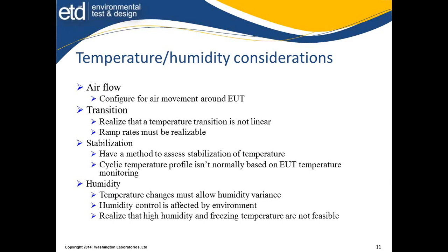Realize that with humidity, temperature changes must allow for a humidity variance, especially if these temperature changes are somewhat rapid. You've got to change, the humidity will vary, and then you can recover it maybe, but it's going to change at some function. So realize holding a solid humidity while we change temperature, especially with rapid changes, isn't real.